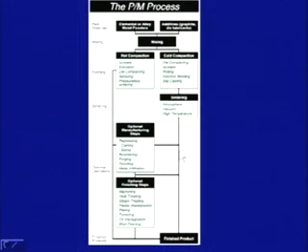As we can see, after sintering either we can come down to the finished product, or there are certain other processes which can be used to give the product its final properties. These are optional manufacturing steps. Either after sintering we use the product in its desired form, or we pass the product on to these optional manufacturing processes. These optional manufacturing steps are repressing, coining, sizing, resintering, forging, re-rolling, or metal infiltration. Sorry, this is not retrofitting, this is re-rolling. So again, these are repressing, coining, sizing, resintering, forging, re-rolling, or metal infiltration.